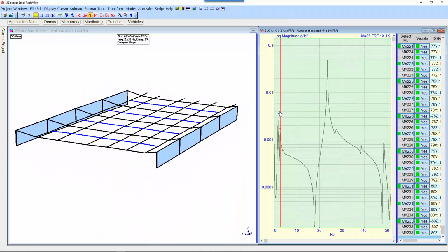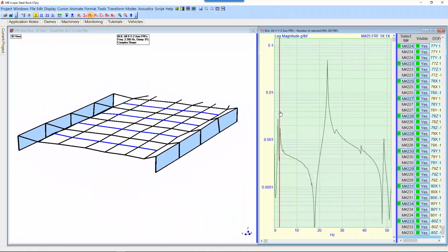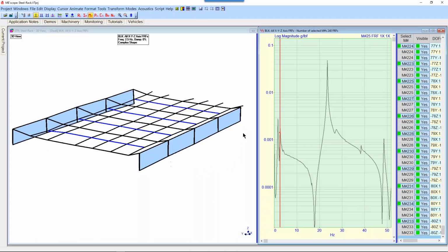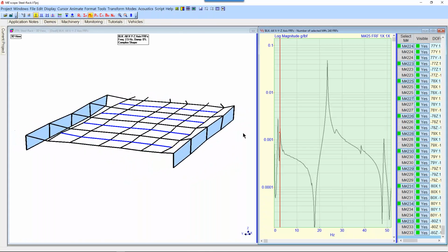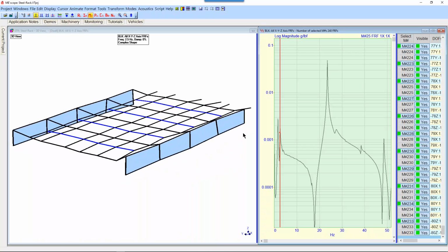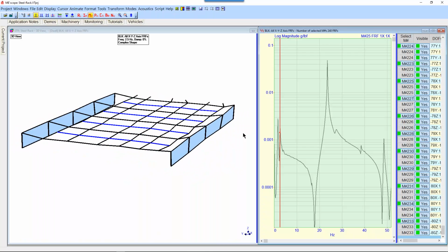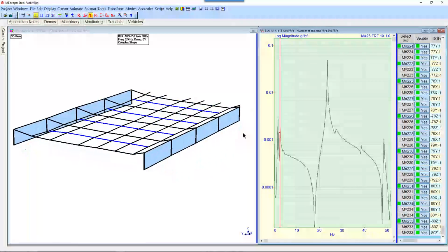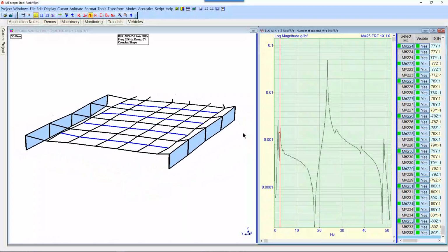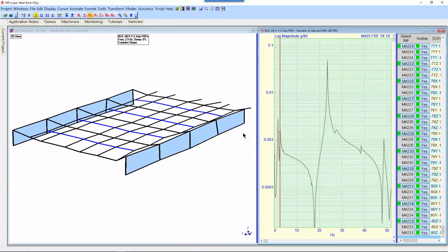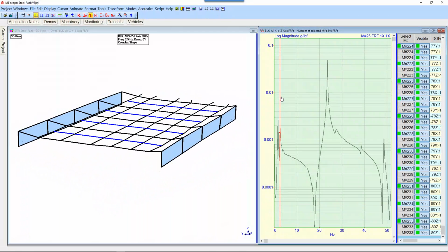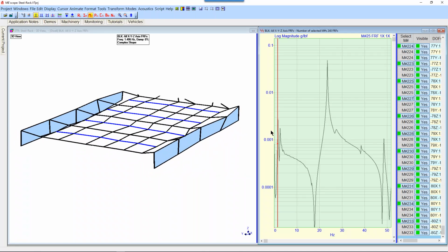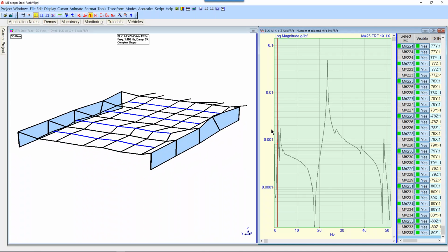And what I want to do is just look, this is a lot of data, so I want to go down here at one of these peaks and put the cursor on there and see whether I have a good set of data. And this is what I'd call rigid body motion. This is the grate just moving around on its base, whatever it is. Think of it as a mass on a spring, and that's a pretty good indication that, at least in the X direction, this X direction set of data looks pretty good. Now if I move it to that other peak, not so good.